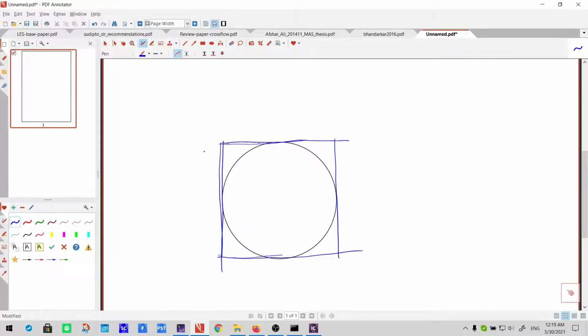because we want a structured mesh, so every cell will be a rectangle or a square, whatever you want it to be. So the full geometry is also to be mapped in such a way that this kind of cells can be generated. This is the very first process for any geometry to be blocked. A block can be generated, and that block will be exactly mapped.